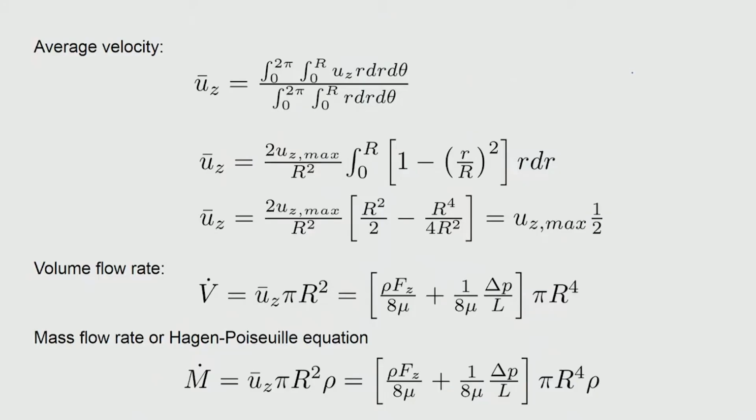So, you know that the area element is generally given in the cylindrical coordinate system as r dr d theta, and so you just take that area element and integrate over the entire circular domain, which means that theta is 0 to 2 pi and the domain is defined by this, and in the numerator you actually have a functional form for v_z. So, that also if you substitute, then you do have an expression coming a little more elaborate.